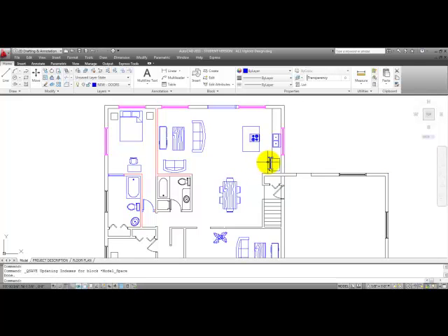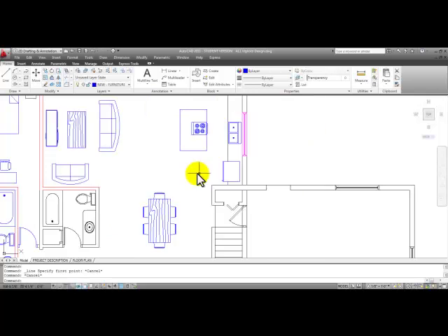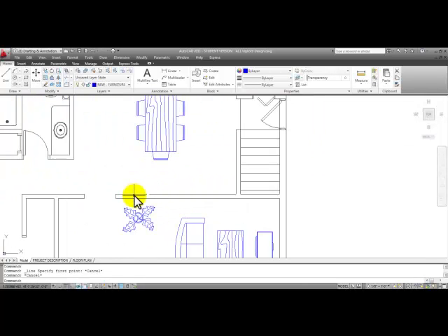Using the same type of commands that we've been using in class, you can clean up the drawing a little bit here using grips to select the line and bring it back to a different spot, and then making the layer current, start the line command, rest your pointer at this point, pull your mouse down to this point, left click, and then left click across. So you can clean up the drawing a little bit.